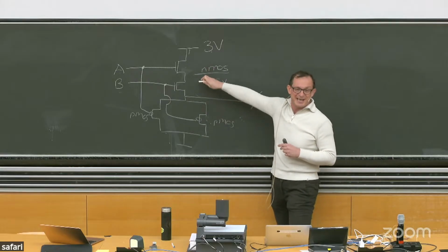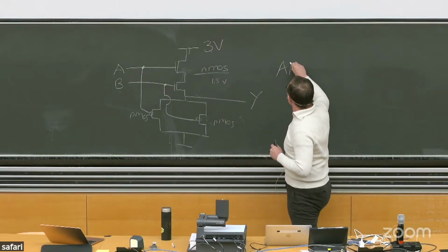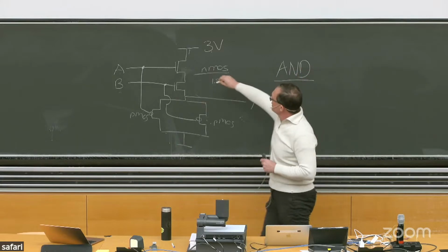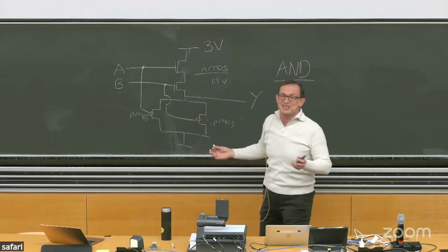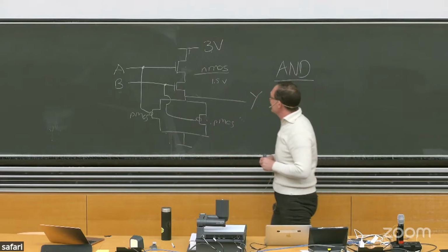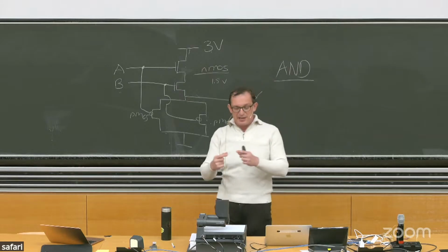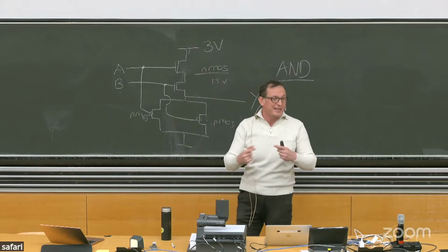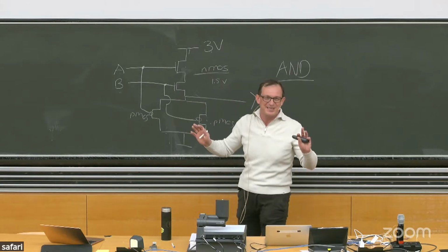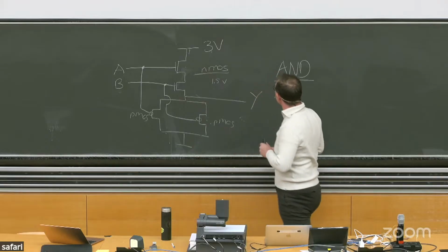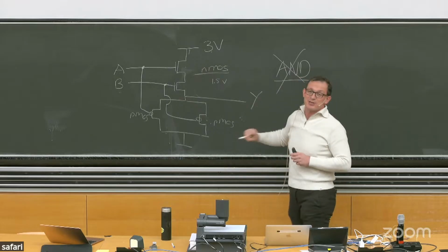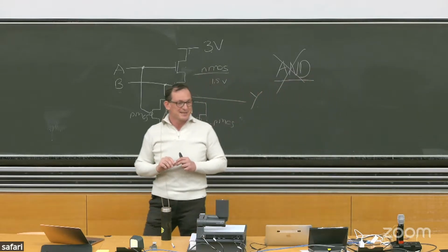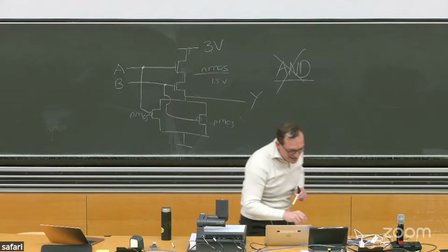You can build an AND gate like this. But transistors cannot work as a perfect switch because of their analog operational characteristics, and the reason is really whether they transmit holes or electrons, as I will mention, but I will not go into a lot of detail because it's really analog circuitry after this point. This AND gate is not acceptable, at least using PMOS and NMOS transistors. Does that make sense?